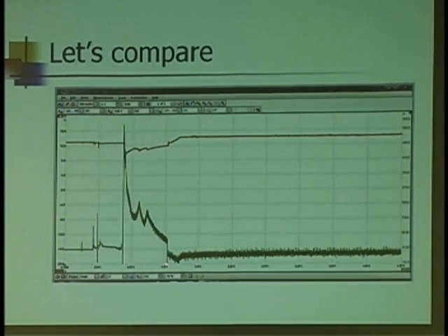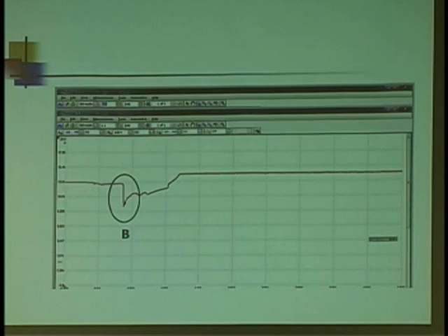Then right here, it drops off. Now the engine is running on its own accord. And you see that battery voltage that we took out, we're starting to put back in. Right there. Right in this area here. This one didn't take too long to come back up to speed. Typically, you'll see that upward slope take a little longer before it gets up to full charging voltage, which is, of course, what we're seeing here.